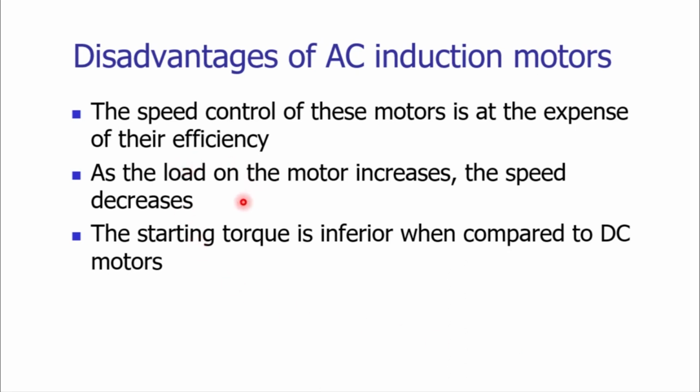If you increase the load on the motor, the speed will reduce. That is a limitation of the AC induction motor. The starting torque provided by the AC induction motor is less as compared to the DC motor.